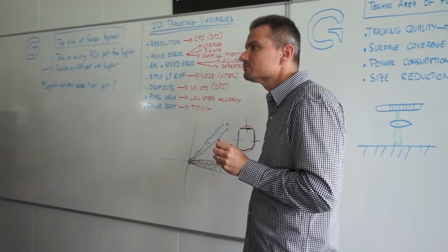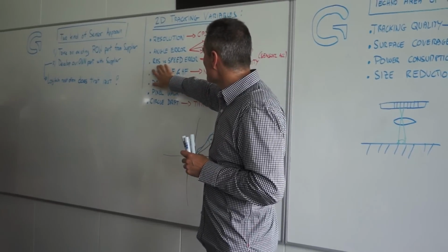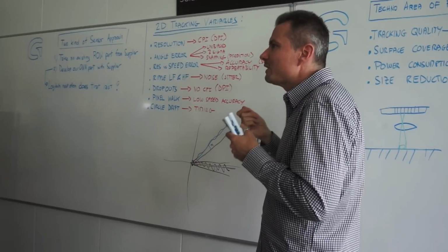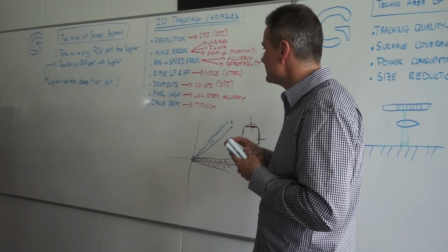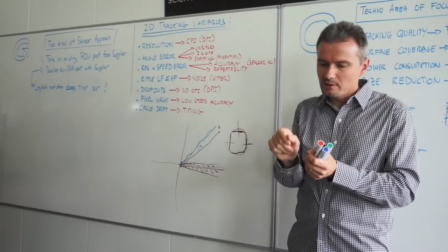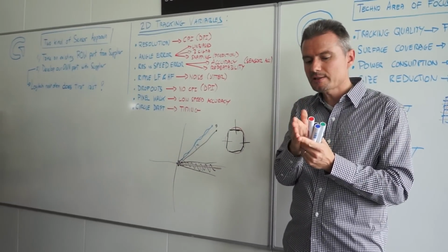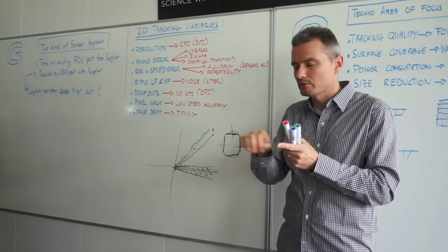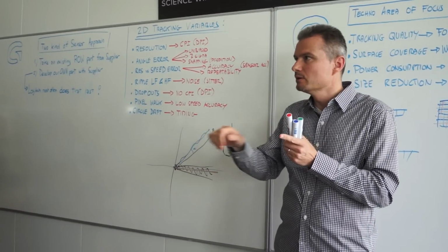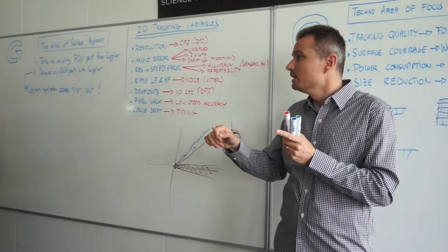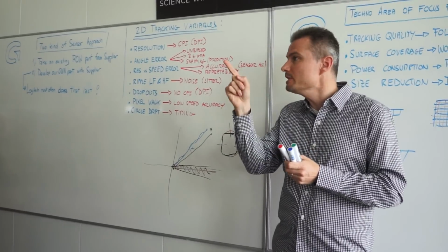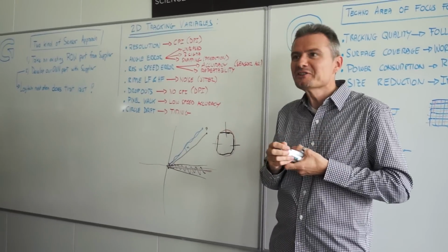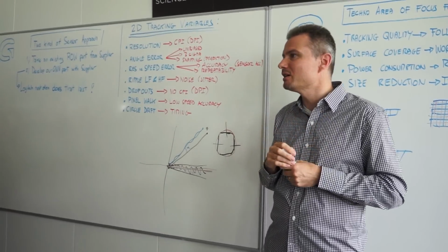Any question? Okay. So then there is what we call resolution versus speed error. Resolution versus speed error, for me, it's really sensor accuracy and repeatability. What does it mean? It means if I take my mouse on the table and I move it very precisely from one position to the other one, I cover always the same distance, let's say 20 centimeters. I do 20 centimeters, I do it at a low speed, and I do it at a fast speed. I should normally see on the screen always the same displacement if my system is accurate. And believe me, again, there are differences. And this is one point where the sensors are not equal.